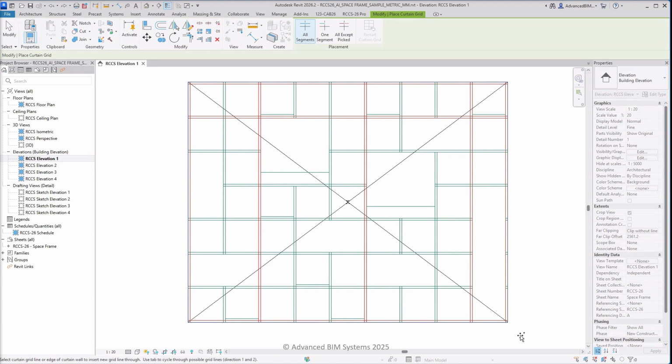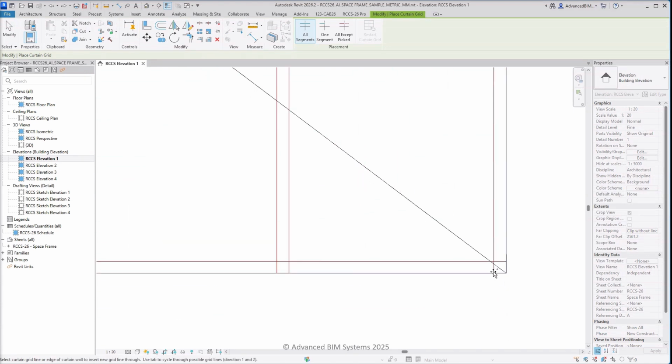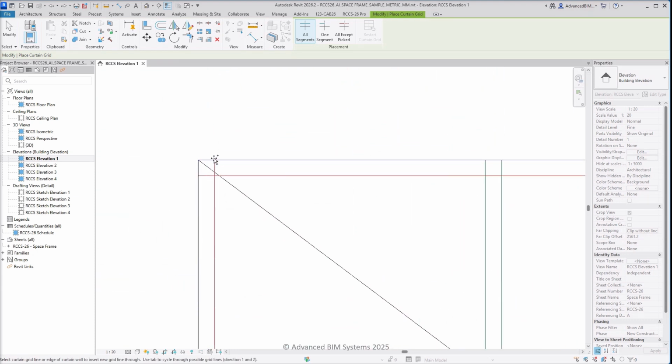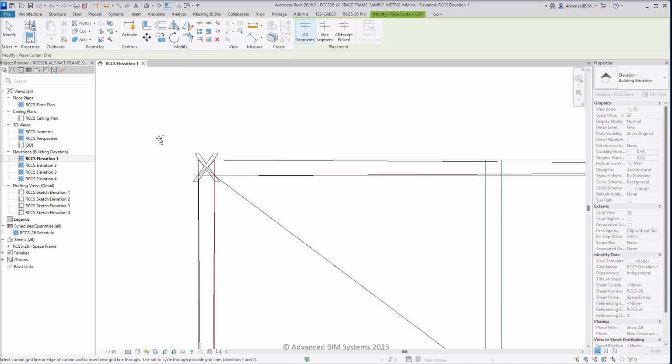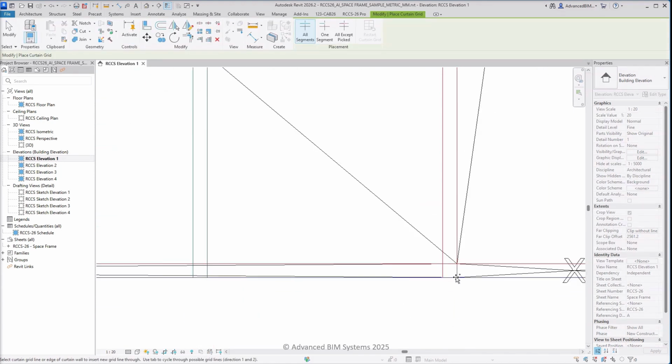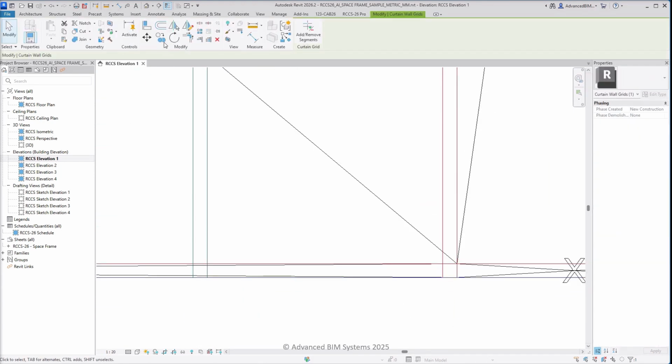To begin a space frame model, start by adding the outermost grids first, around the perimeter of the design. The next step is to add a single grid, which can then be copied to make a grid pair.